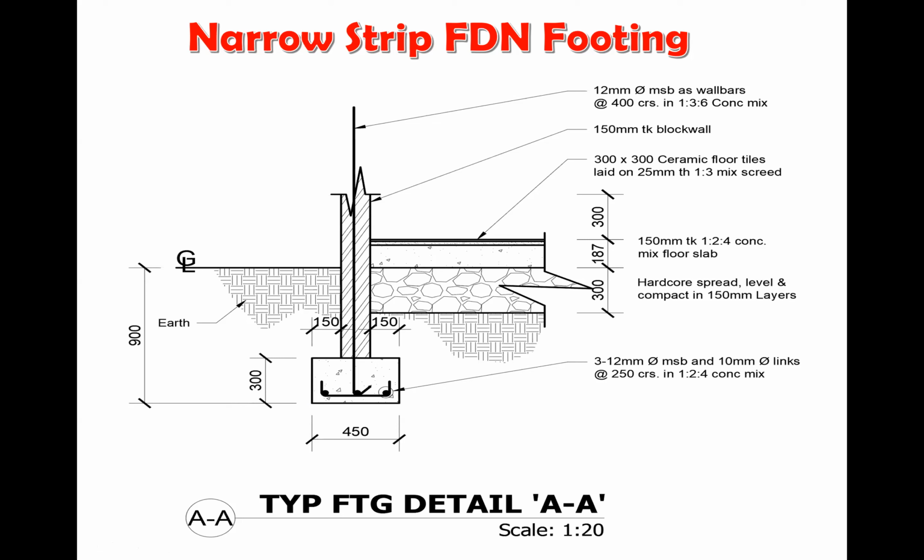Now, what do we call good firm soil? Maybe you have red dirt, black soil, sandy loam, good firm strata, not anything that has water in it readily, like a swamp area or any clay type soil. So this is not recommended for clay. Since I mentioned the word clay, I'm just saying it outright right now. Everybody understand that this type of foundation is not recommended for clay. So we're going to talk about some other types.